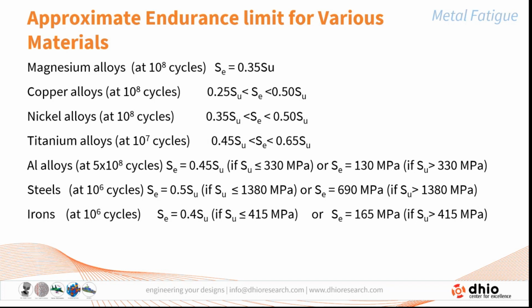Is it possible that a material will still have a finite life if the number of loadings is very high? We are having repeated loadings that are very high, but the stress is below the endurance strength we have derived. Is it possible that the material can still have a finite life? Yeah, definitely. Because it also depends on the magnitude of the stress induced and the sequence in which it is acting and the speed at which it is acting.